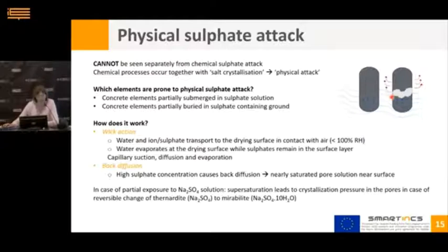In case of sodium sulfate attack, you have in fact the crystallization of the salts that can occur in the pores. And due to the changing environmental conditions, temperature and relative humidity, you can have a phase transformation from the thenardite to the mirabilite. And just by having this reversible change, you have the crystallization pressure that leads finally to degradation of your superficial layer. So this is the first part about that.